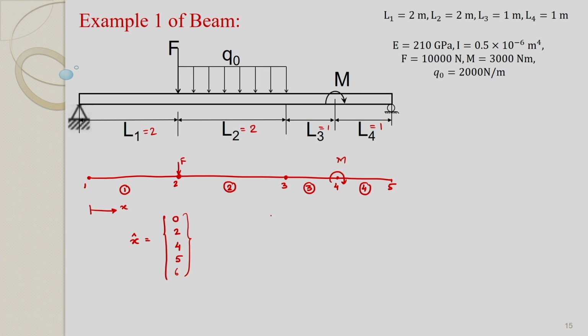And for this problem, boundary condition at x equal to 0, your deflection is 0 and your moment is 0, it is free to rotate, there is rotation.